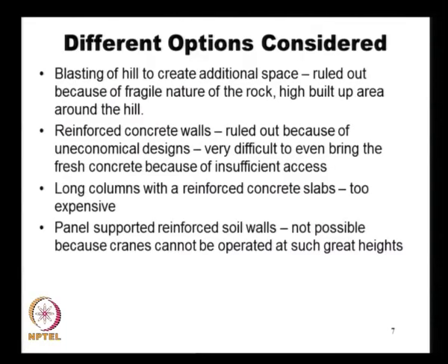And in this particular case, we can consider different options, like we can create a wider road or a parking space by blasting up the hill to create the additional space, but that is ruled out primarily because the fragile nature of the rock does not permit controlled blasting, and also the entire area around the hillock is highly built up.